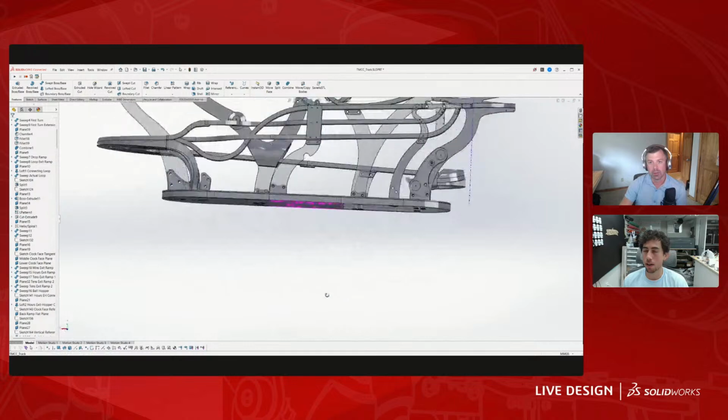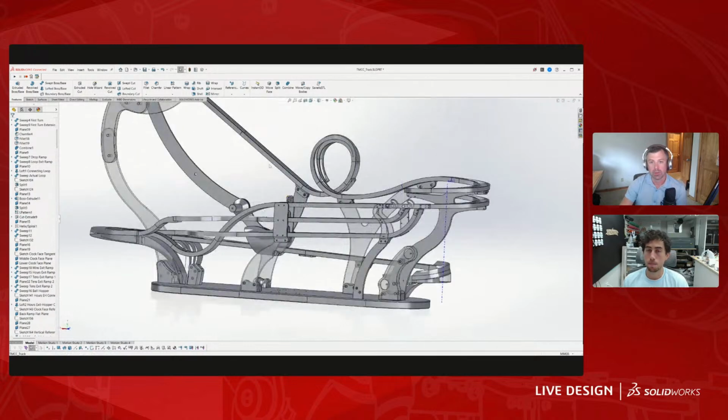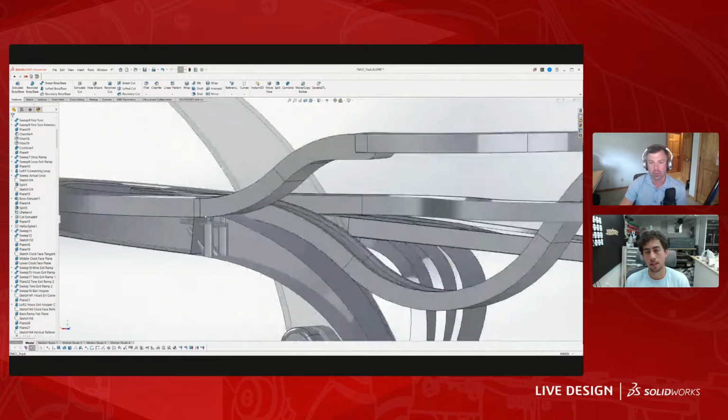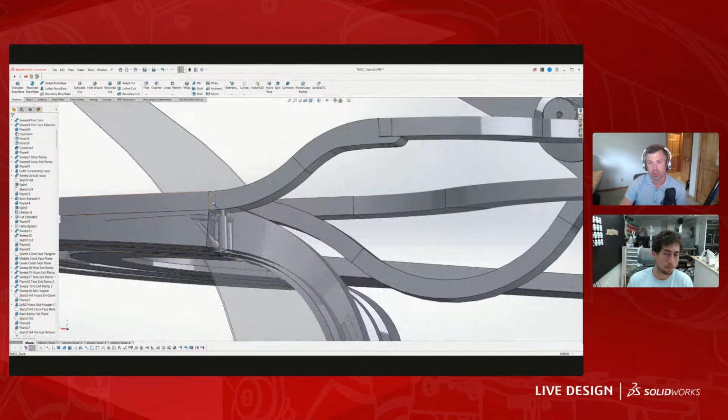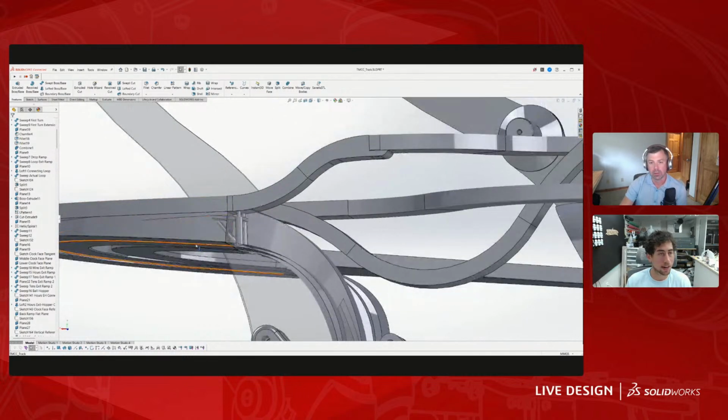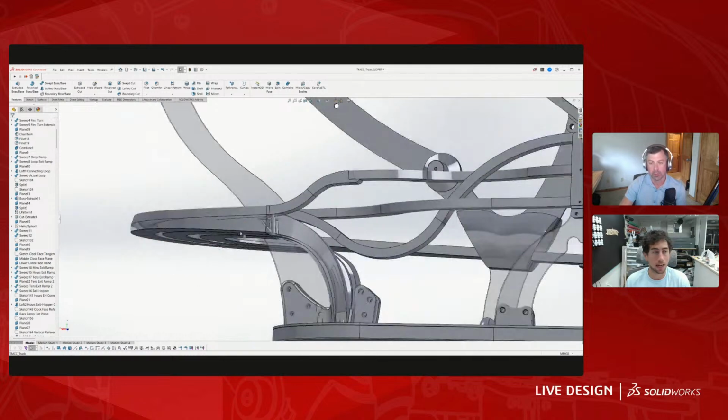But yeah, a lot of times I'll just thread screws right into 3D printed parts, and from my experience, it works really, really well. A lot of people use threaded inserts and heat set them in. I've never done that. I've never had a problem. Even regular metric screws, I'll just thread them right into the part, and they hold really well. You kind of undersize the holes.